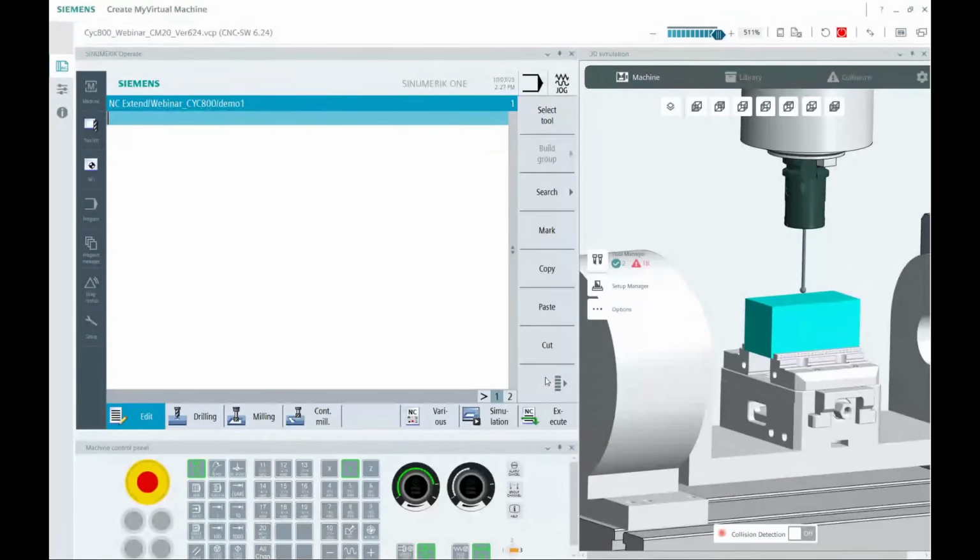So my normal programs would always start with some kind of a safety line. This is no different. So maybe I want to make sure I'm in absolute mode. Maybe I'm in G17 plane mode. What is my unit of measure? I'm going to be in inch in this case. Certainly it could be metric. What is my work coordinate, right? So I'm using G54. That's pretty common for a standard safety line.